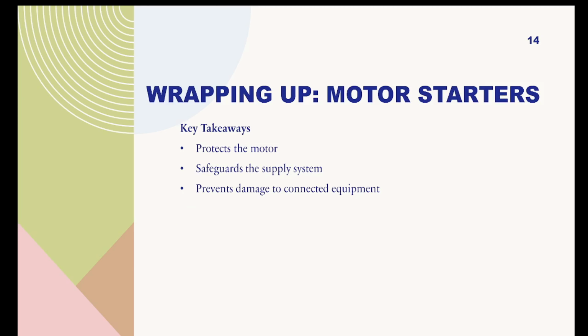So today we learned why motor starters are essential. They protect the motor, the supply system, and connected equipment from the harmful effects of high starting current. In the next video, we'll take a closer look at the DOL, direct online starter, how it works, and when you should use it.